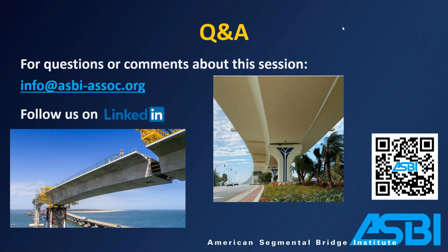Yeah, and the main thing that it doesn't have, that an in-service routine inspection risk model would, is the current condition. There are no attributes in here discussing what the current condition of the bridge is, and usually an in-service model would have something like that. Obviously if there's rust staining on the soffit of the bridge, the likelihood of corrosion damage increases quite a bit as compared to not having rust staining. So there's no current condition in this model, and my suggestion would be if you did an in-service model, you need to have a couple attributes that describe what the condition is now.